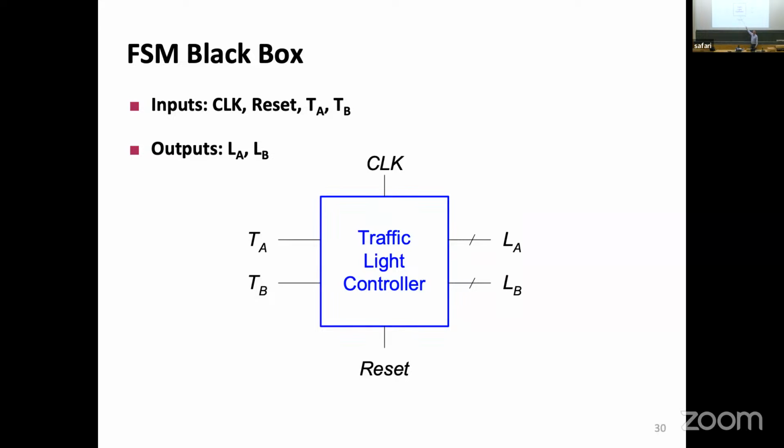Internally, I have a state, and this is not combinational. I will not be able to determine what the state of the lights are just by the current input, because if the light is green, I first have to switch the other light to orange, then the other light to red, make sure, then switch the first light to orange. There's like a progression of things happening. It doesn't happen instantaneously. This is why I need those states in between.